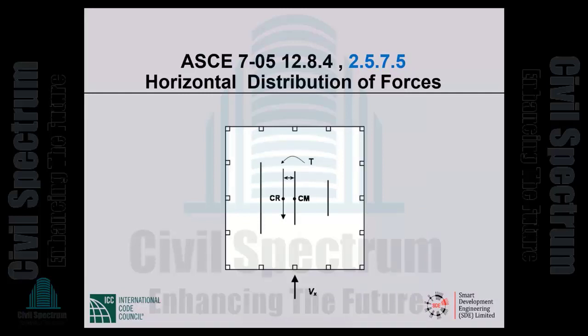Okay. Now the story shear acts through the center of mass, which is pretty much at the geometric centroid of the plan, because mass is, I keep on saying, mainly in the floors and the roof, not so much in the vertical elements like the columns and the shear walls. Okay, so the fact that this shear wall is longer than that shear wall does not move the center of mass from the centroid of the section.